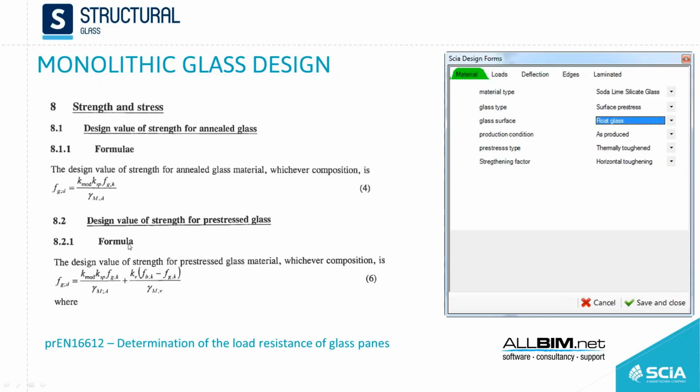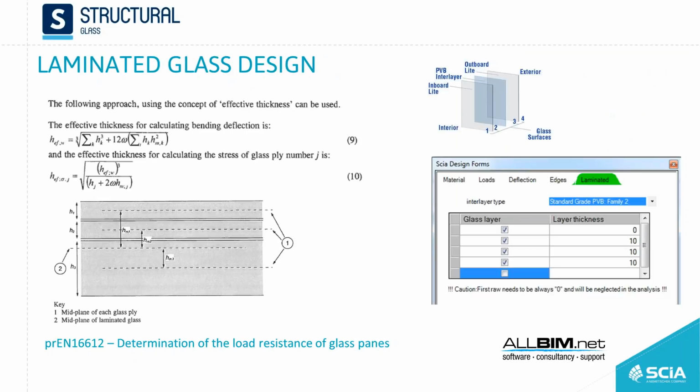And when the glass gets tension, first the tension will consume that compression, and only then will it tension the glass. So this is the idea of prestressed glass, and this is why there are more parameters that go into the determination of this capacity. You'll see that there are different parameters we can choose when we talk about the factory, and this will give values to all these coefficients. Our formulas are also transparent inside the software, and we'll see that in the practical examples.